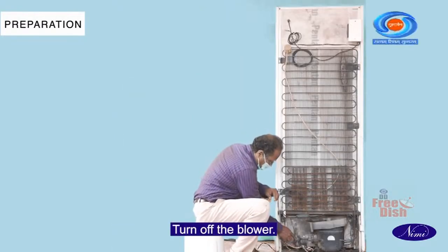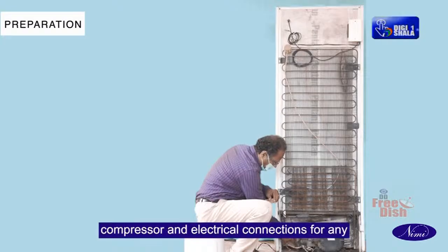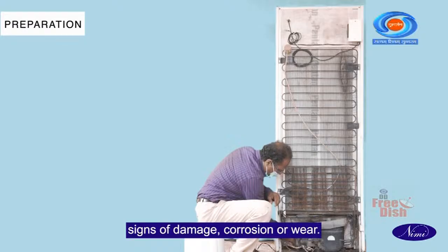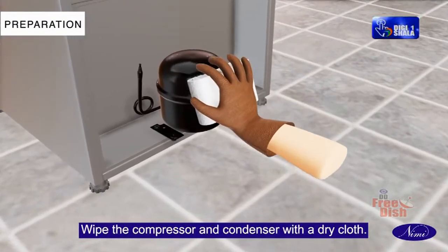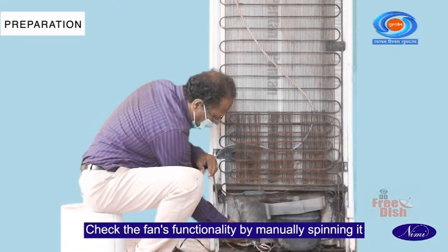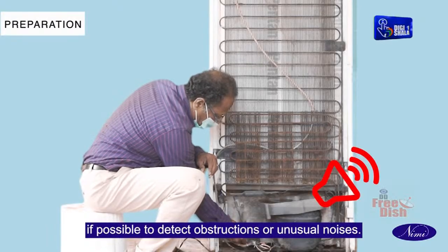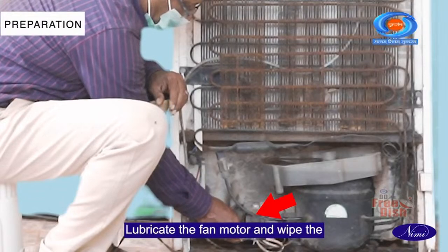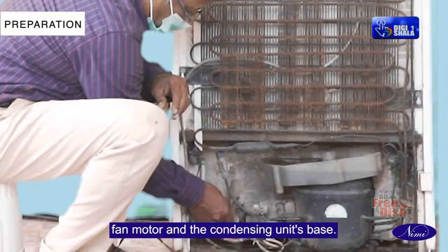Turn off the blower. Inspect the condenser coils, fan blades, compressor, and electrical connections for any signs of damage, corrosion, or wear. Wipe the compressor and condenser with a dry cloth. Check the fan's functionality by manually spinning it if possible to detect obstructions or unusual noises. Lubricate the fan motor and wipe the fan motor and the condensing unit's base.